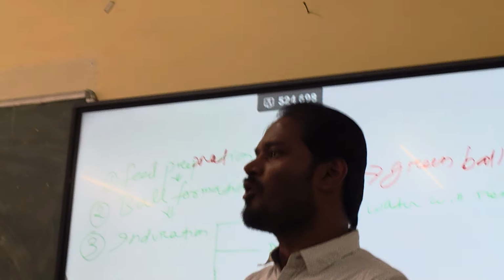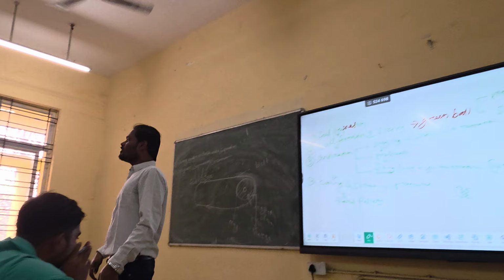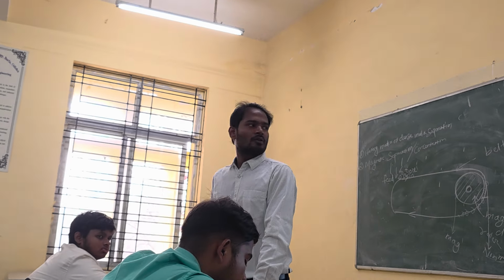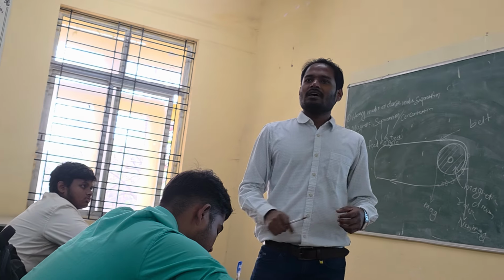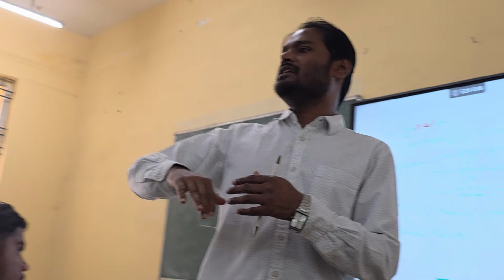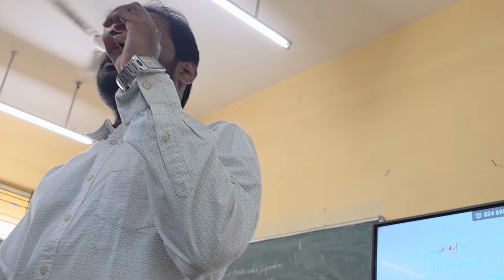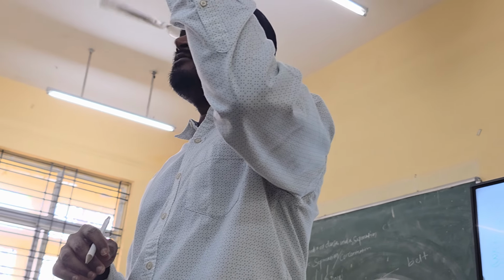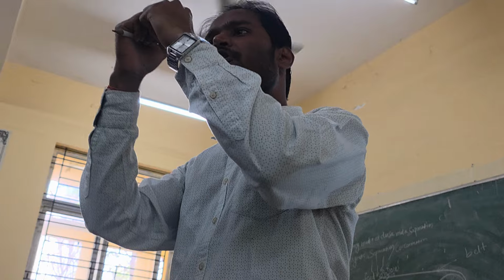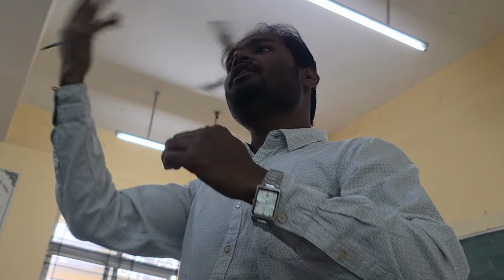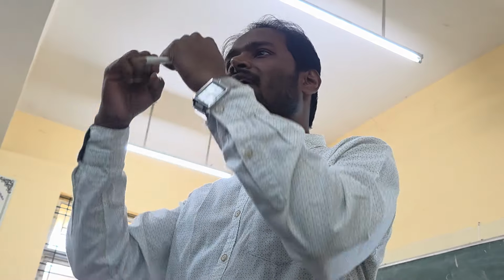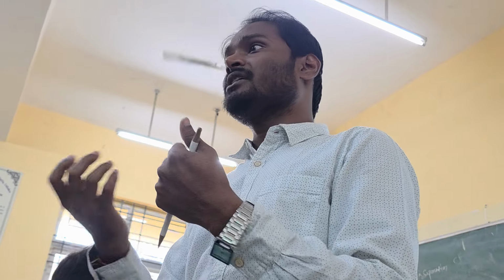Two types of bonds basically form during your firing. Solid state bond means, suppose you take one solid particle and another solid particle, put them together close to one another, and heat them. After some time you will see that they got bonded. The bond will form automatically. In the solid state, you are not taking it to liquid, but still the bond will form. You will study a subject called powder metallurgy in your coming semesters, maybe in the 6th or 7th.